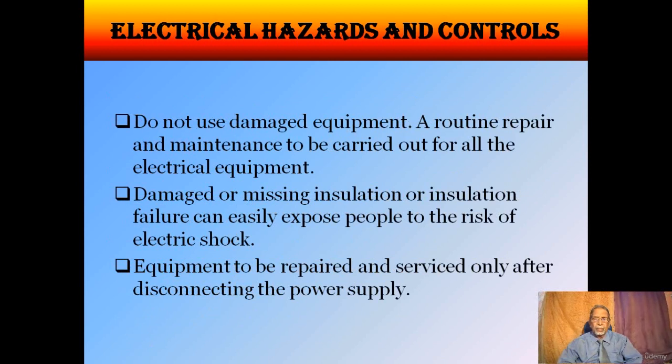Another thing is, don't use damaged equipment. Check the equipment to see whether it is in good condition or not. If there is some damage or any errors with the equipment, do not use it. Send it for repairs. So you should have a program for routine repair and maintenance to be carried out for all the electrical equipment, and you should maintain a log for that.